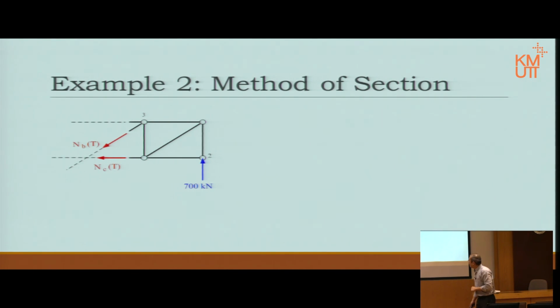Now we are left with NA, the axial force of member A. Now we're going to look at the point where we can take moment and eliminate NB and NC, the unknowns. In this case, that is where it cut. At the point where it cut, I will call it point 4. If I take moment about this point, don't worry about this. Remember the proof of the moment: if it's in equilibrium, everything is kind of coupled. You can take moment anywhere. It still has the same thing. The summation of moment on that body about that point must be 0.